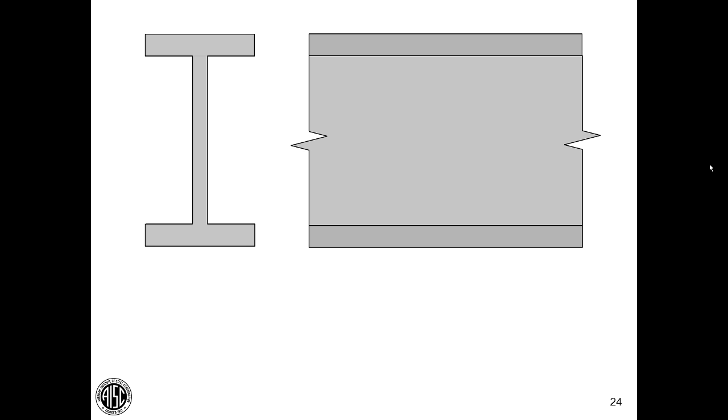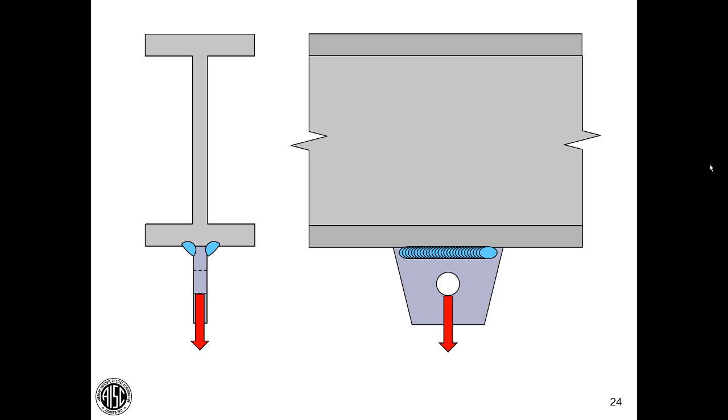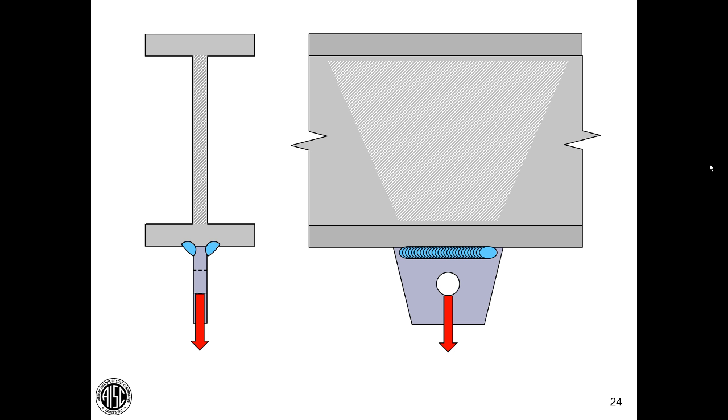Here we have a beam, and we're going to attach a lug underneath the beam. Of course, we're going to weld it in place, and now we apply the load. Mr. Blodgett says the force goes into the member that lies parallel, or that we should provide a path for the force to enter into the member that lies parallel. The parallel member in this case is the web, and ultimately that vertical load is going to enter into the web. It goes directly through the welded connection, and the welded connection is uniformly loaded along its length. And here we have a good connection detail.